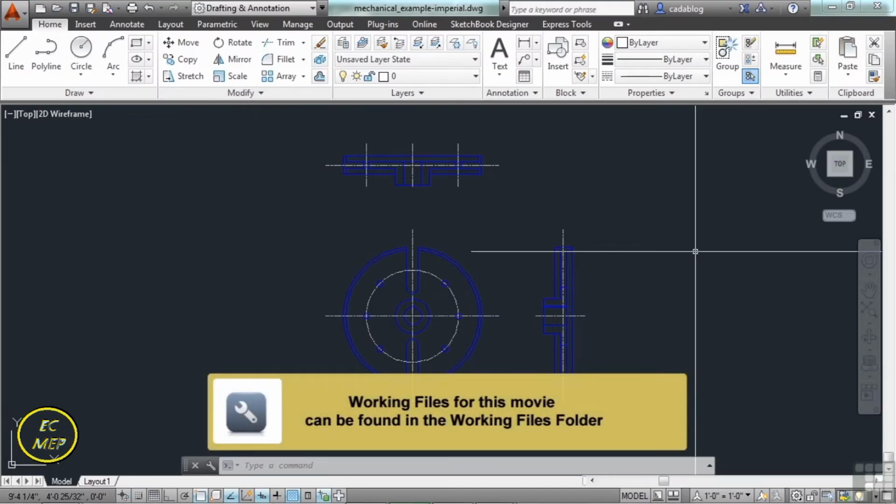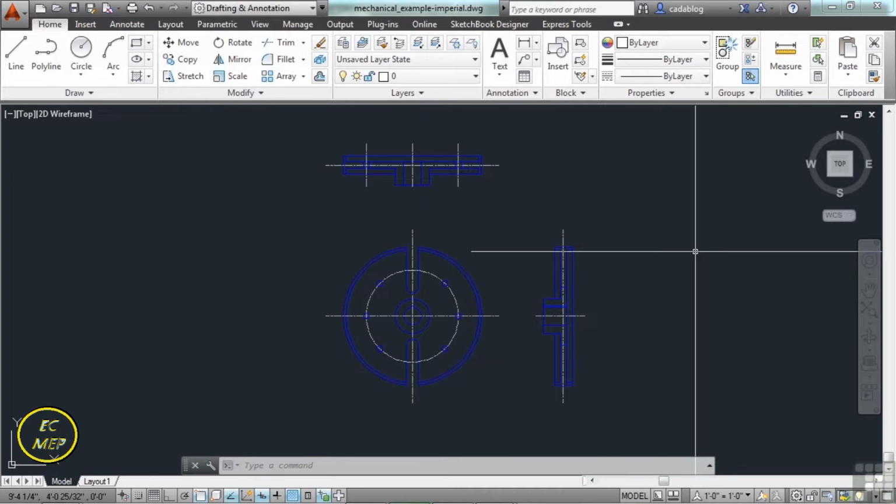When you make a drawing, it is designed in some sort of linear measurement. Most of the world uses the metric system, while other places like the United States use the imperial system of feet and inches. AutoCAD doesn't really know what those units are. It only sees generic units. Drawing units are relative to AutoCAD. It will only interpret the units when you go to print your drawing or when inserting other AutoCAD files or blocks. It will translate your drawing's units to fit the way you want it to look on paper.